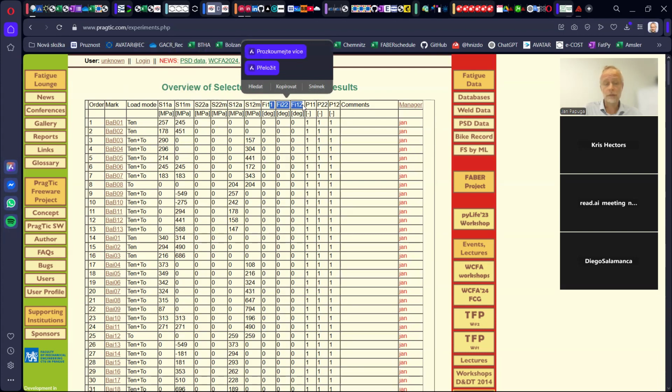If there are three load channels, it means usually there are three independent actuators or pressure valves or whatever else, which induce loading in separate modes on the specimen. And there is also a period, because it can differ.